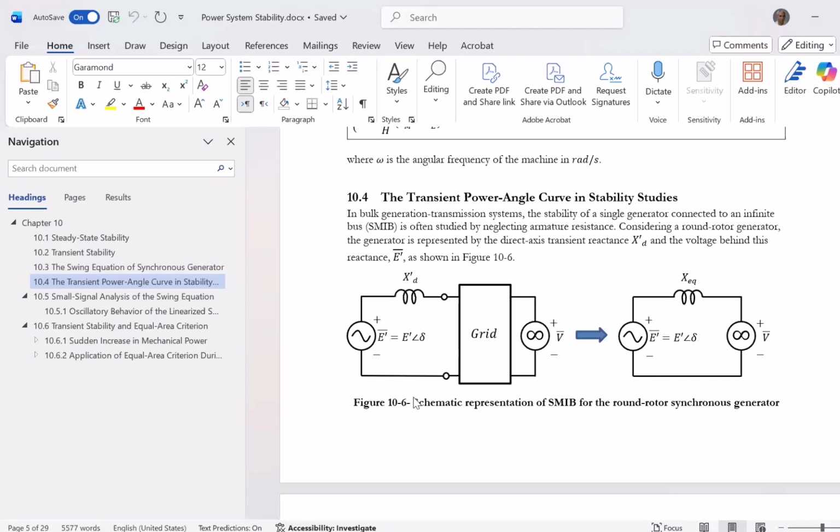You call it under equilibrium point, which means power flow. You find the power flow, find the voltage at this point, how much power your slack bus is giving to the grid, and then you come up with the calculations in this loop to find E prime and delta. That's what this means, and we will be seeing that in the examples coming forward.